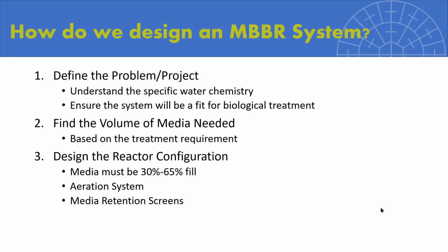But we also want to check to make sure that the project you are looking at is a good fit for a biological system. This doesn't happen very commonly, but sometimes we do get clients who may come to us and say, hey, I have a system at this flow rate, and here's the COD and here's the BOD, and we don't know anything else about it. Not all COD is created equal, and we saw a very high COD to BOD ratio, which caused us to ask more questions, and we found out that this is coming from a glass facility.